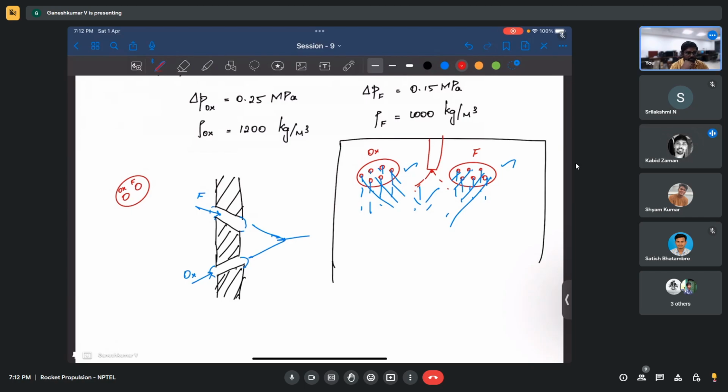Right, right. Now, what about liquid propellant rockets? Do we need a large igniter like that, or can a small igniter be more than sufficient? You can think of it like SI and CI engines. So what do you do in SI and CI engines? In CI engines, you don't need an igniter because at high pressure it automatically reacts, right?